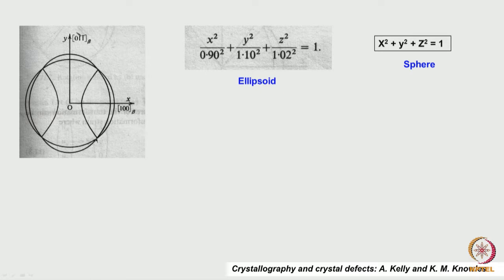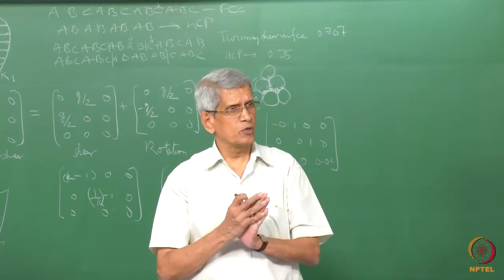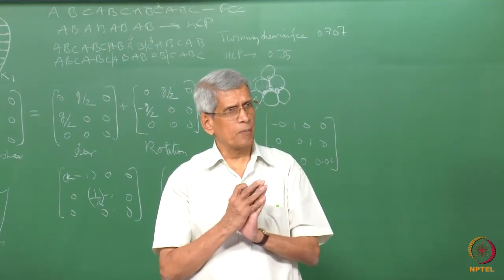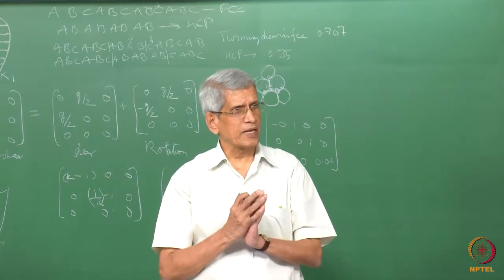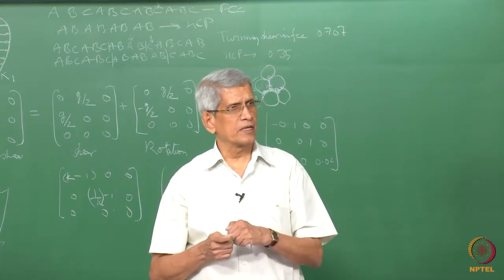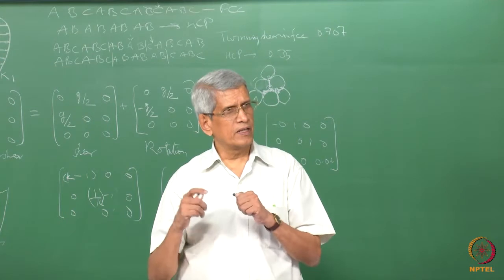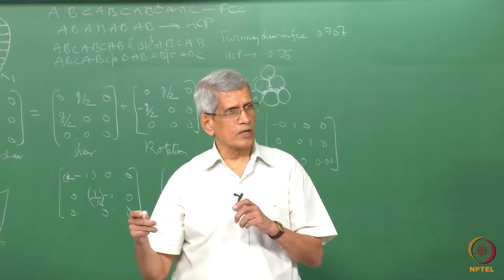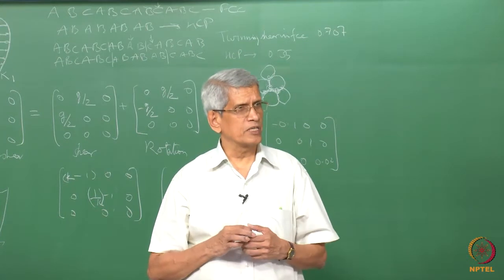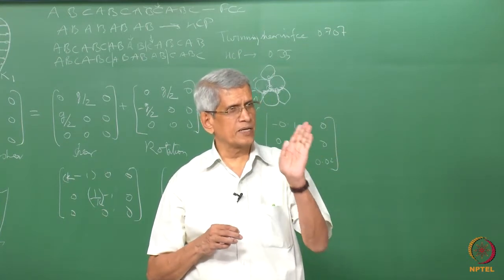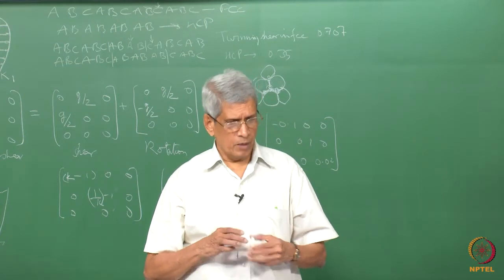Okay. That means that for a simple shear, or homogeneous shear, which we have considered, there is a plane, correct? For that plane to be generated, if we are applying strains along principal directions, one direction contraction, one direction expansion, keeping the volume constant, then that plus a rotation can be equivalent to a simple shear, so that a plane which is unrotated and undistorted will come. But that will not happen here.